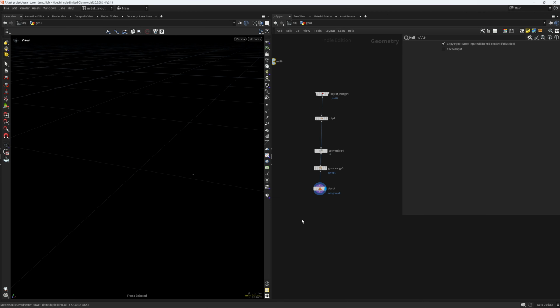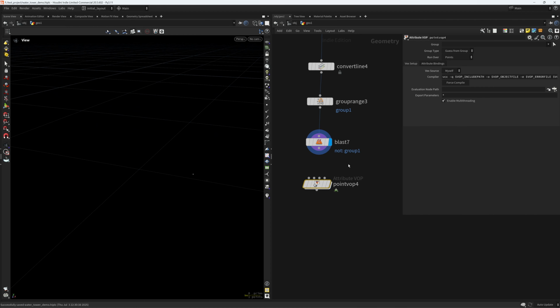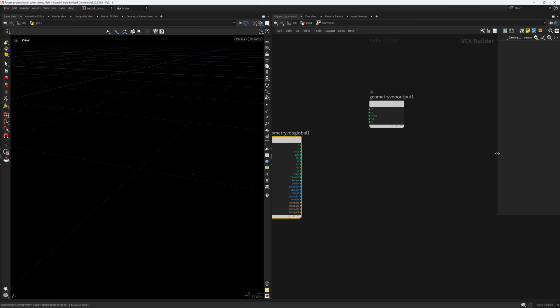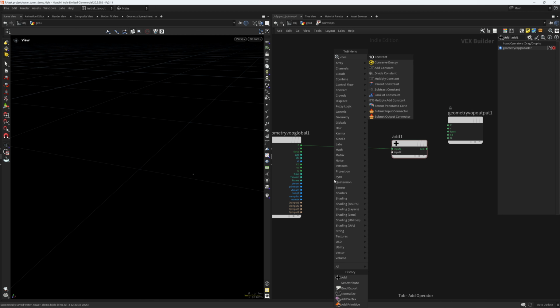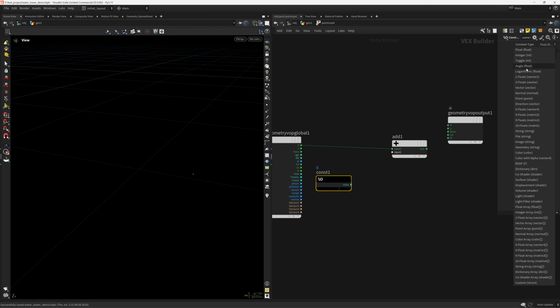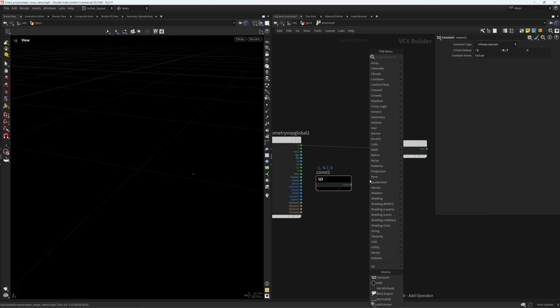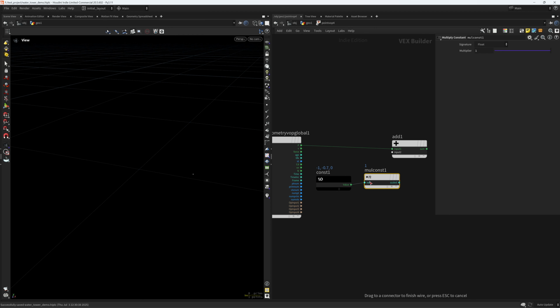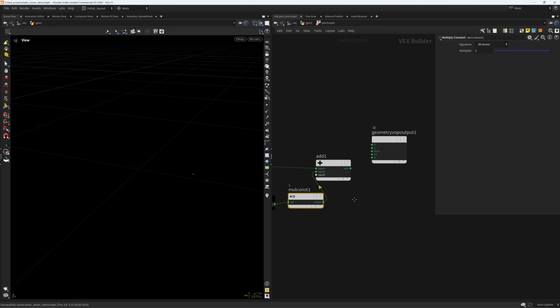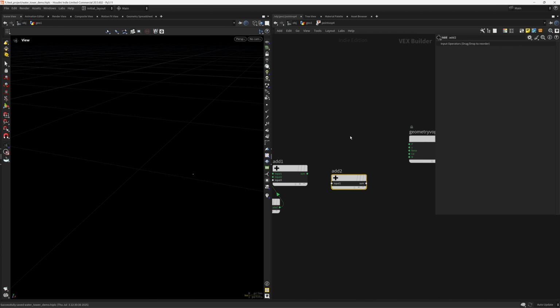So now let's manipulate this in point pop. So this will be pretty simple. We're just going to take the position and add to it, and so now you know how to do this. Set this to vector, and I'm gonna move the first point along the negative x-axis, and also a bit down too, so 0.7, and I'm gonna multiply constant and add this in here, and add point.